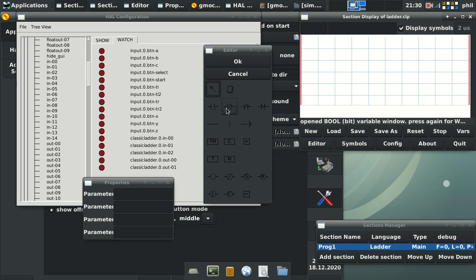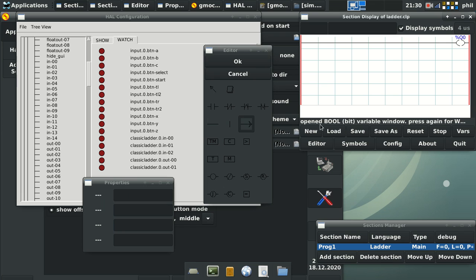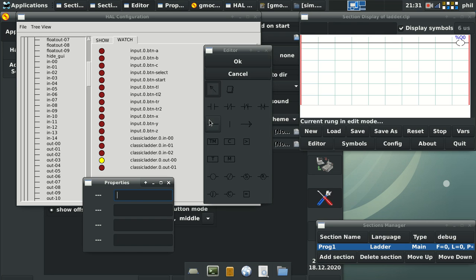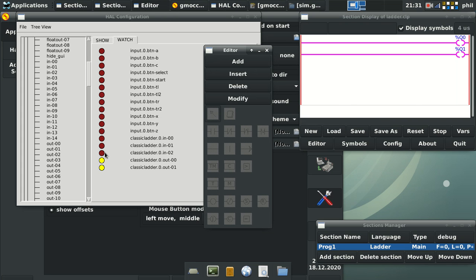So getting into here, the first thing I want to show you is if I just assign an output with a straight line from the input side connecting to the output section, and I hit OK, you see that the circuit is being made with the pink line and that the output is being triggered within the watch list. I'll do that again underneath, connect it with a line, use the object selector to select the output and give it the name of Q1. When I hit OK, both of the outputs turn on, both of the signals connect.